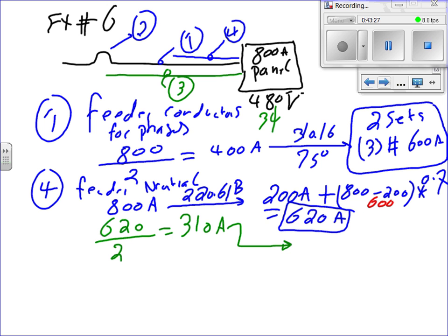We take this one to table 310.16. So if you take it to table 310.16, what do you get? Do we get 350? Right? I need another gentleman other than me to say 350. Okay. I didn't see it, I just guessed it. 350, how many sets? 2 sets of 1 conductor, 350 kcmil.